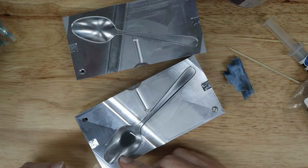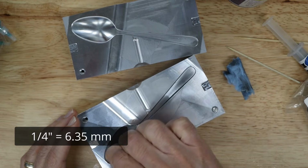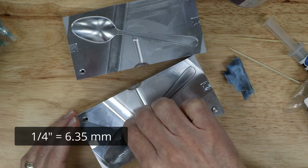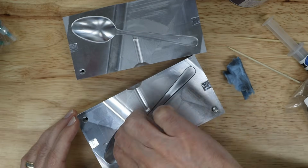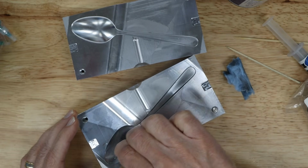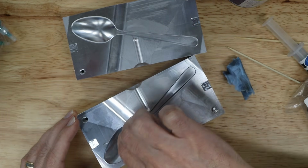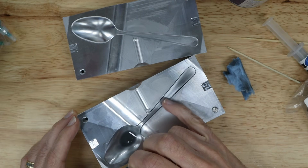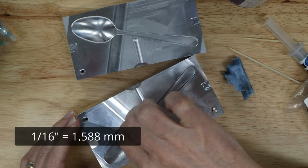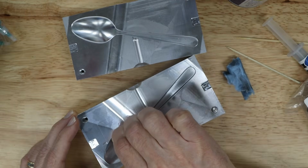Now in this section here, I cleaned up with a 1/4-inch ball mill. And so the 1/4-inch ball mill, I think, has slightly greater distance between the cusps. So I'm not sure if it'll clean up as quickly. We'll find out shortly. Whereas over here I used a 1/16-inch diameter ball mill, so much closer spacing.